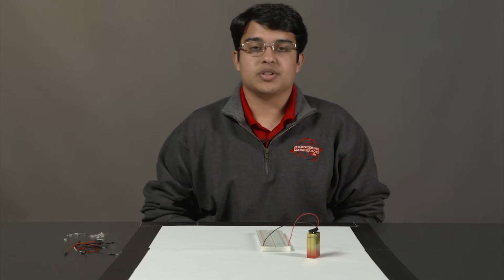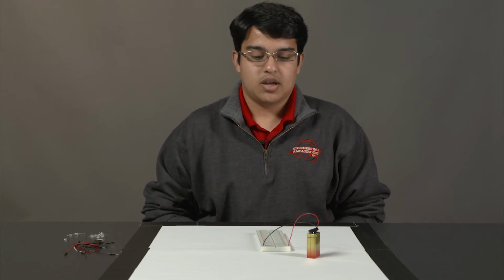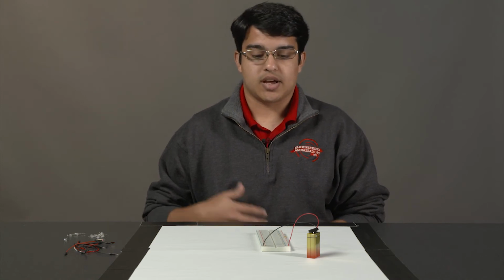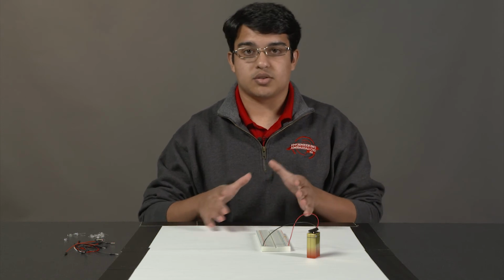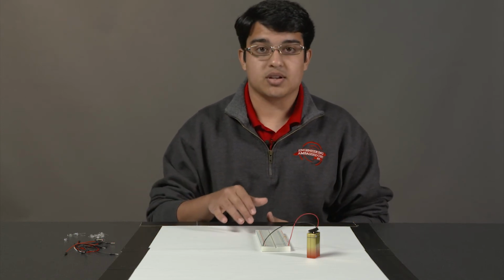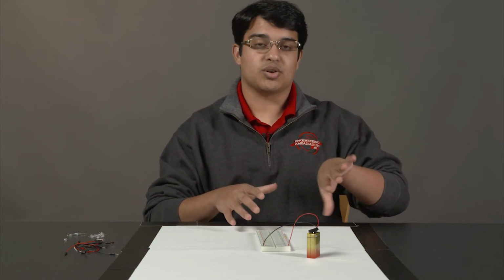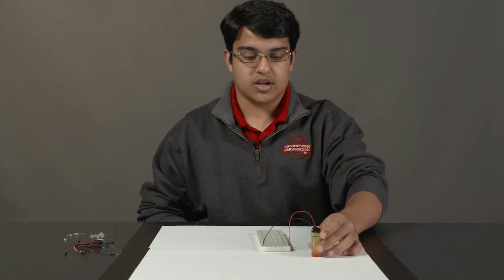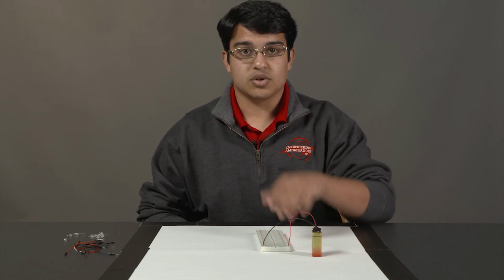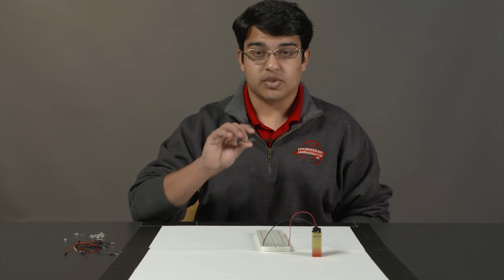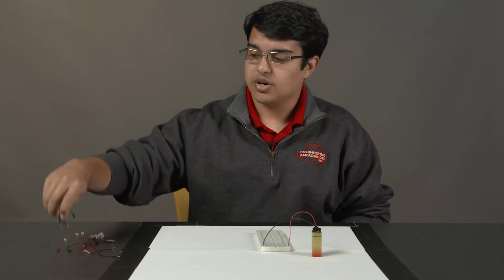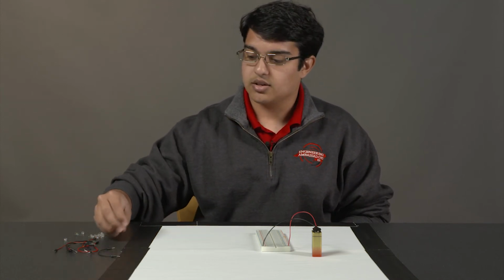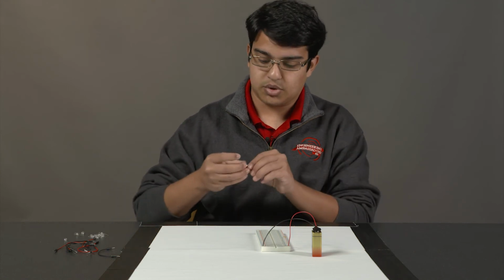Okay, now I'm going to demonstrate activity 1.3. Now this activity is more of a challenge. We're going to try and see if we can build a circuit that has 2 LEDs that are on to begin with, and then we will press a button and we want those first LEDs to turn off and a second set of LEDs to turn on. Now for this activity, you're going to need, again, a 9-volt battery and a battery clip, a 470 ohm resistor, a bunch of LEDs, a bunch of various jumper wires, and you will need 1 push button.